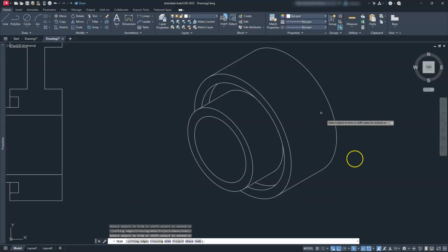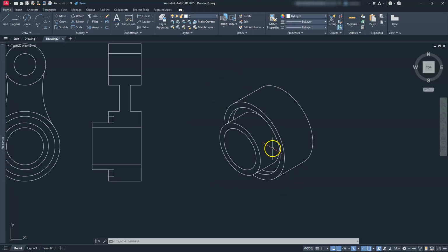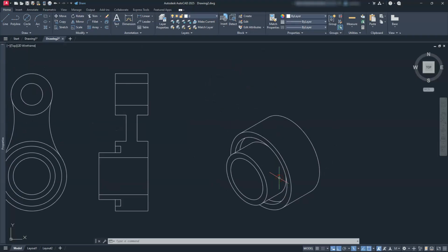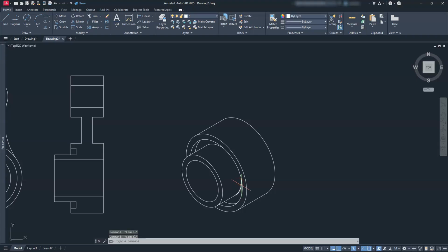And now if you take a look at it, you can see that we do have our shape created here. Exactly what we want to do. We have this part protruding out and it goes to a certain depth, stops here. This part flares out to here and it comes up and then it wraps around and does exactly what we have pictured there. Okay, now let's work on the top part. Let's draw a line from this center here in the back and go up a distance of 75.